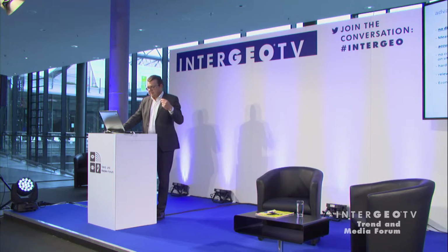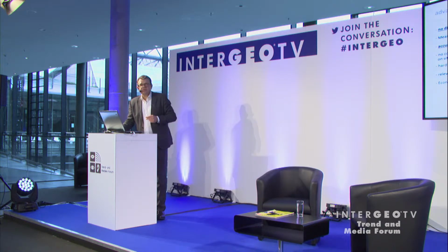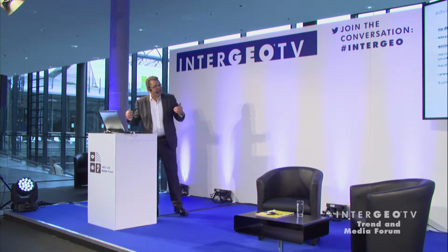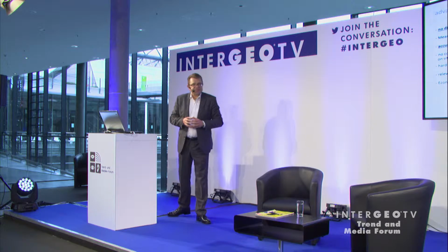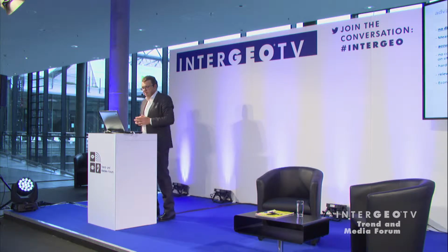The real advantage of fiber optic sensing is that you don't have to define discrete points in advance, and that you can also go into the object. For example, you can put the fibers in the concrete. With the new tunneling methods, we put the fiber sensors in the concrete when they are erected. You also have no more sensor infrastructure on site.